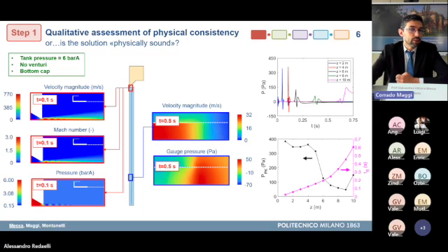The intermediate color plot represents the Mach number, and you see that the values of the Mach number are well above 1, indicating that the flow leaving the nozzle is not only highly compressible, but also very supersonic. And below you can see the color map of the pressure distribution. And here you can identify the small diamond-shaped blue part and the blue parts in the very bottom of the color plot. And these are a well-known phenomenon of supersonic air jets.